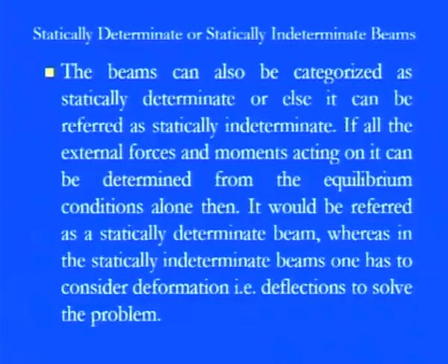And the other is, you see, we have a simply supported beam in which the reactions are there. If we have the pin joints at both ends, this will allow this particular beam to move under the application of load, either in the bending side or the shearing part. So we can simply take the reaction forces in the x as well as the y direction, these two mutually perpendicular reactive forces. And another form of the simply supported beam is if you have rollers, then definitely the reactive forces are coming in the perpendicular direction, irrespective of whether this pin joint is the straight one on the roller or this pin joint is the tilting part.